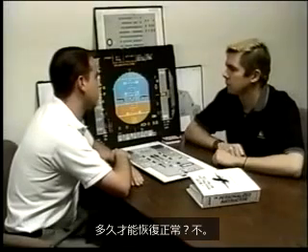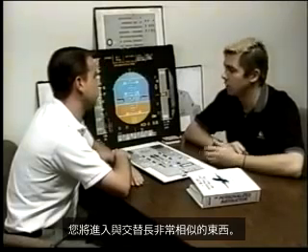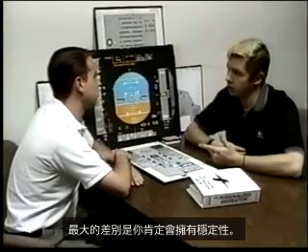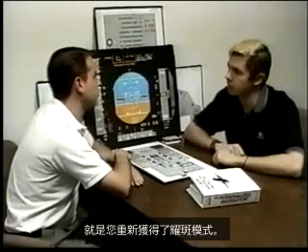Do you go back to normal law? No, you definitely don't go to normal law. You go into something that's very similar to alternate law. The big difference, you're definitely going to have stability, you're going to have yaw dampening, but the biggest difference is that you get flare mode back.